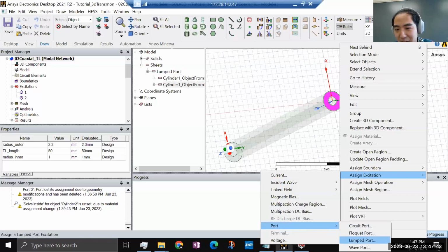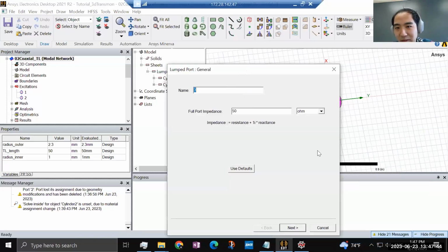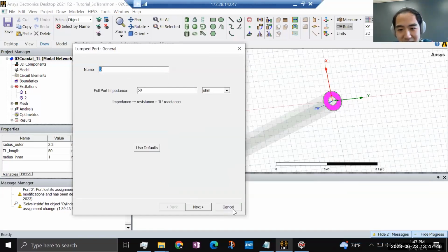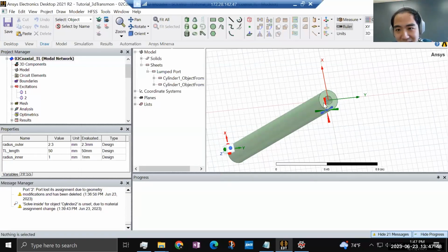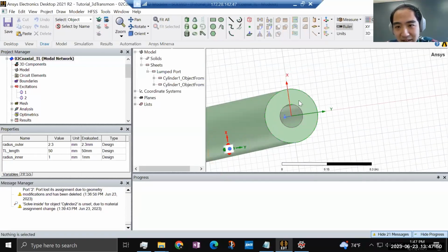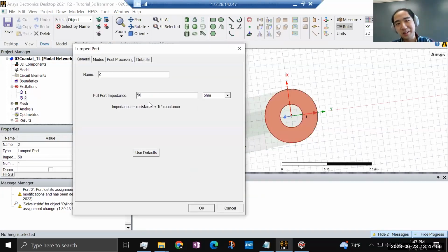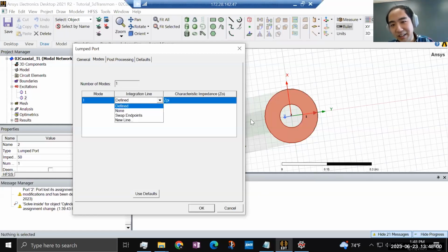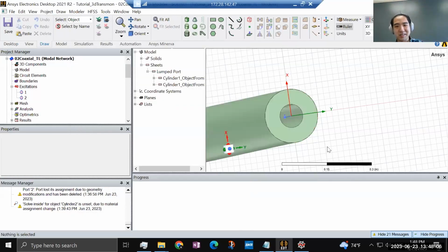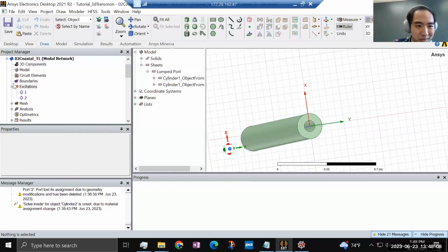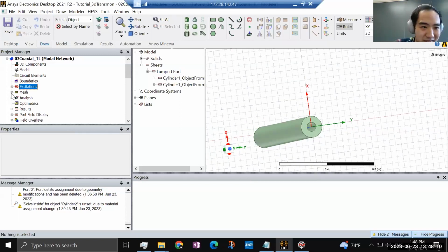And for this thing, I do a lumped port, which is an excitation created with, say, yeah, that looks like this. In creating a lumped port, another trick is you need to define an integration line that in our case is pointing from the inner surface to the outer surface. But okay, these are all details that you should be able to figure out from all the instructions afterwards.